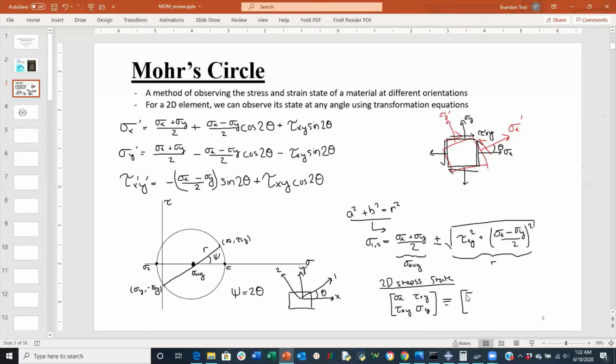And the advantage of this is, one, we identify what the equivalent maximum normal stress is and at what angle an identifiable system is, and 2, we have the luxury of not dealing with shear stresses, which is advantageous for quicker and more robust calculations. So there's a lot of interest in trying to achieve the principal stresses. So that is for a 2D case.